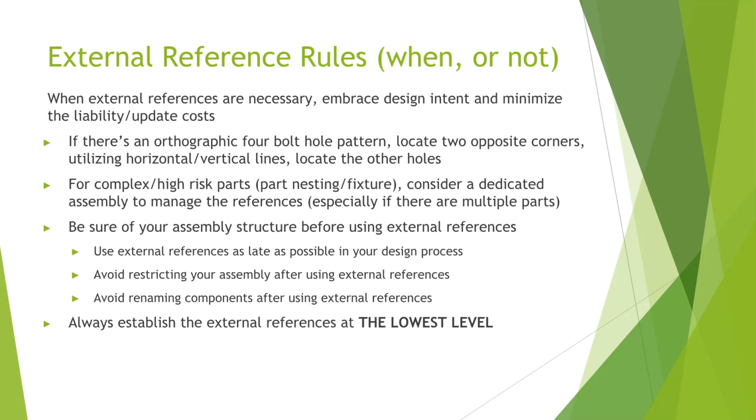4. If instead, and I'll show this as well, you drop that Destaco clamp in and you kitty-cornered, or catty-cornered, depends on how southern you are, 2 external references, opened up that part file, and then drew 2 horizontal and 2 vertical lines and dropped in the other 2 holes, when that Destaco clamp changes, how many errors do you have? 2. The design intent can be embraced, and that's assuming it's orthographic and not at an angle, and there's a bunch of other stuff, right? But when the design intent is embraced, you can limit your risk, and when something changes, the next guy, because again, you have to assume it changes, somebody else is working on it, you're sick or something, it's less risk and less problem for them to resolve.